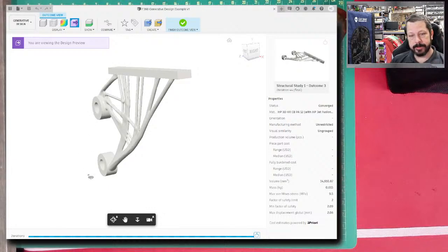So the way that Fusion 360 does this is you create preserved regions and obstacles, and then it builds everything around those. Whereas in SolidWorks, you build the kind of bounding box and tell it some hard-coded regions that you don't want it to affect, sort of like preserved regions, and then it eats away at that. So they're coming at it from 2 different directions.